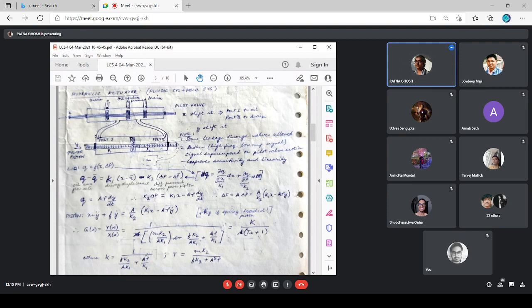Now, from the physics of it, you understand that you can think of Q as a function of X as well as delta P. Since that is so, interpreting it into a mathematical part, rather linear components, this is the expression then: dQ = (∂Q/∂X) dX + (∂Q/∂ΔP) dΔP. Is this much okay? Ma'am, here K1 and K2 are constants.